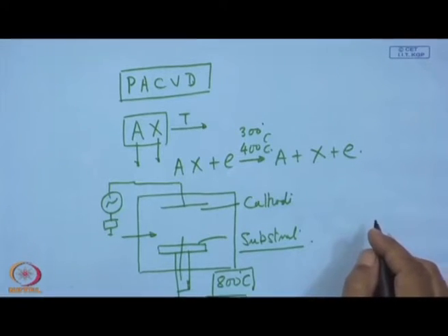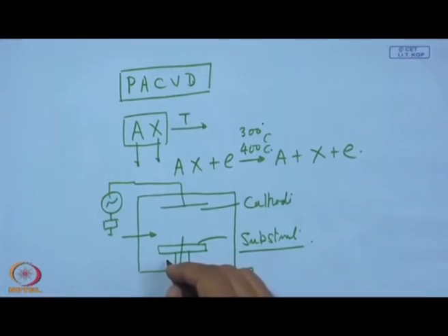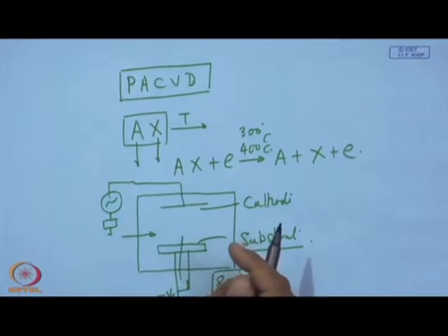And apart from that, if we can also polarize this thing with this negative polarization of the substrate, what is done in routine PVD. In routine PVD, that means sputtering, then ion plating, biased evaporation, all sort of bias sputtering, we routinely use substrate bias, and that is only to have impingement by this positively charged particle ion.